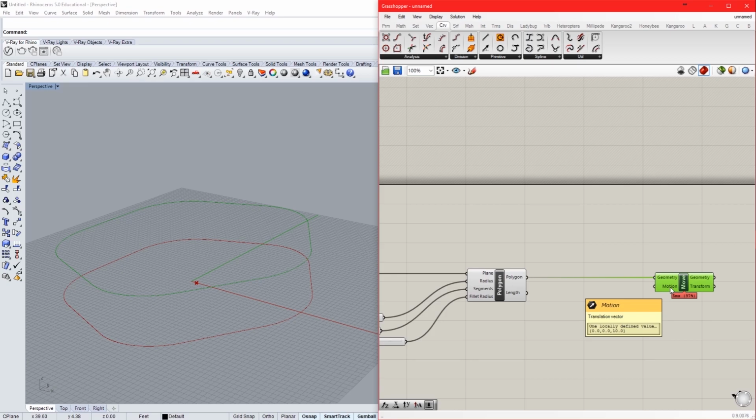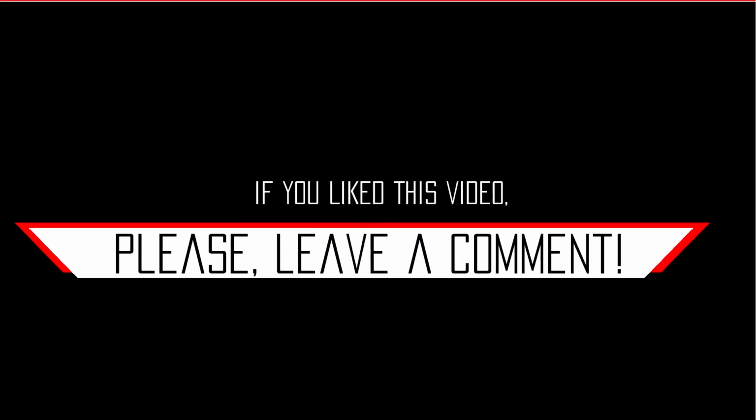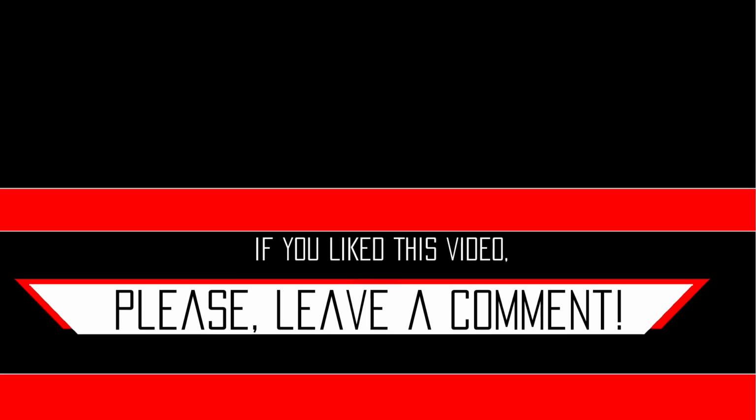But here we have 0.0, 0.0, and then we have 10 in the place where the z value goes. So I understand that this move component has defaulted to moving this geometry 10 units in the z direction. Hovering over these inputs and outputs is always going to give you hints as to what's going on. And if you're simultaneously looking at what's happening in Rhino, you can deduce what's going on here.